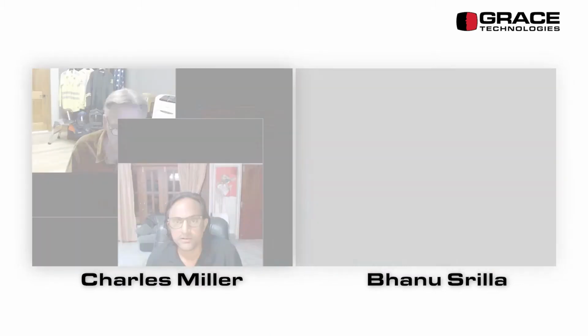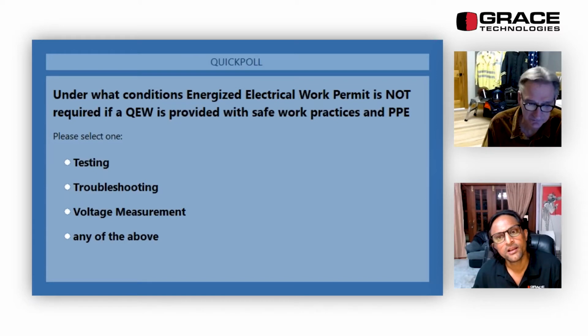So let's go to the next one. Under what conditions is an energized electrical work permit not required if a qualified electrical worker is provided with safe work practices and PPE? So the responses are testing, troubleshooting, voltage measurement. Last one is any of the above.